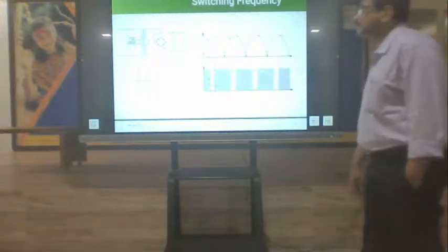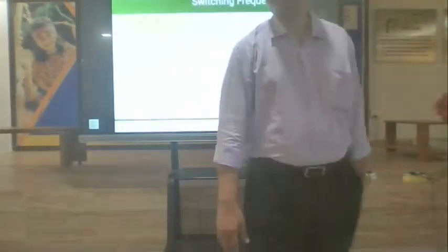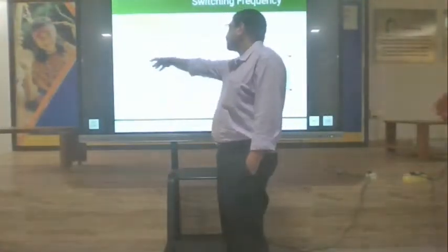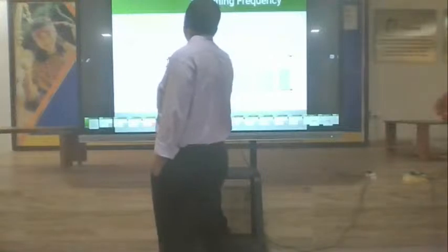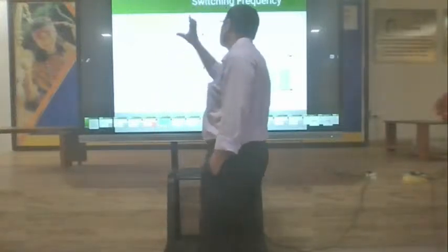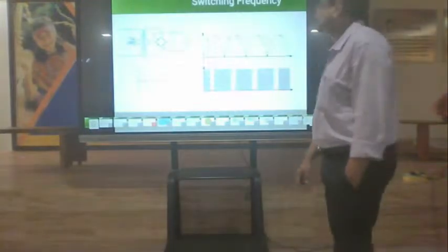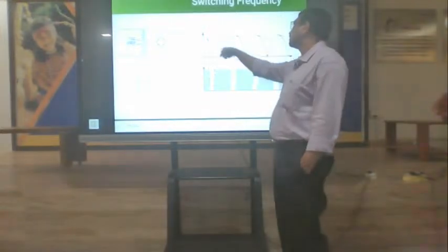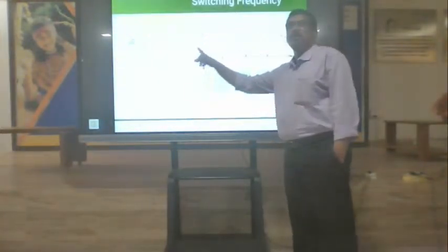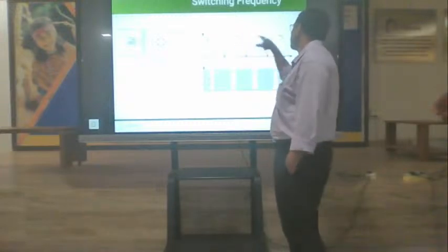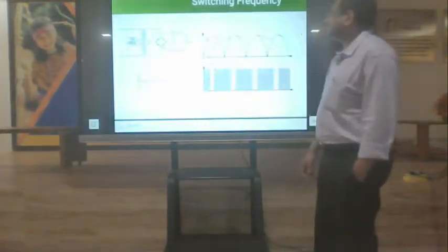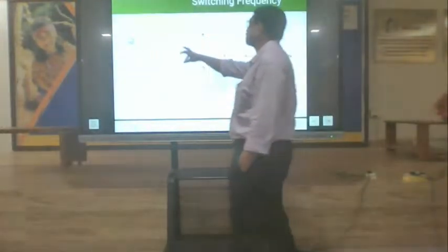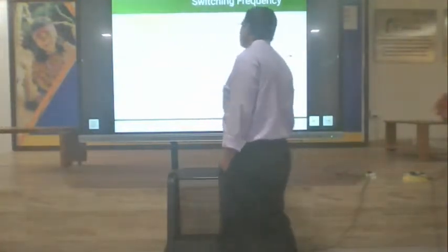Now let's come back to whatever you have learned, I think this year or previous year. So this is basically a bridge rectifier. This is a step down transformer and the bridge rectifier, and then you have a capacitor filter which is going to give you DC voltage across the load, right? So this is the full wave bridge rectifier. You get a rectified AC voltage, and then the rectified AC voltage is applied across the capacitor filter.